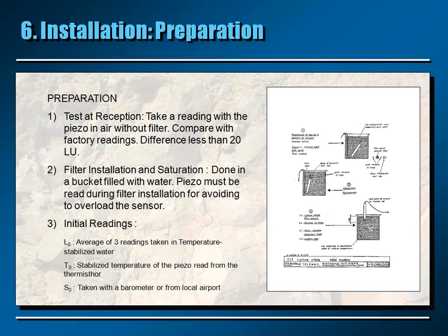The next step is to install the filter. The filter will be installed this way. You have first to put the piezometer and the filter in a bucket filled with water. And then you will simply put the filter in place on the piezometer. If the filter, like the ceramic filter, is already in place, you have to remove it from the piezometer and then make sure that the water got into the piezometer and that there's no air bubbles,